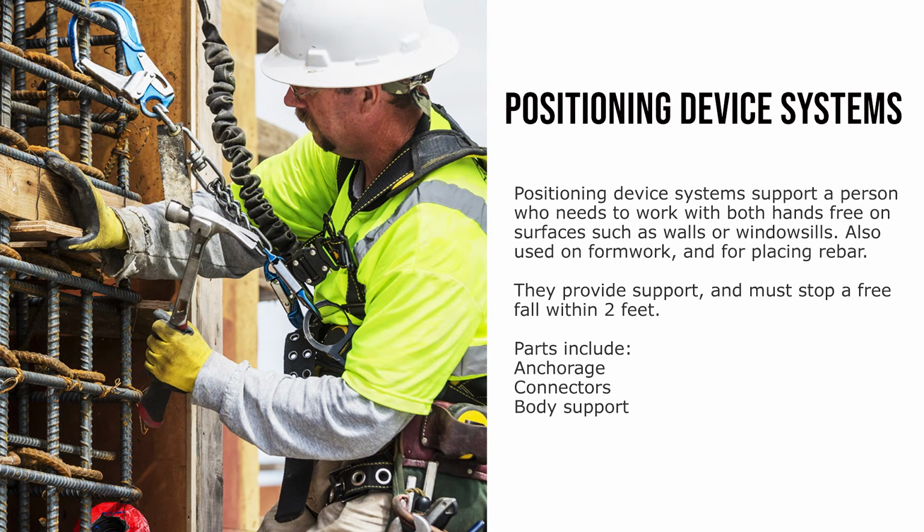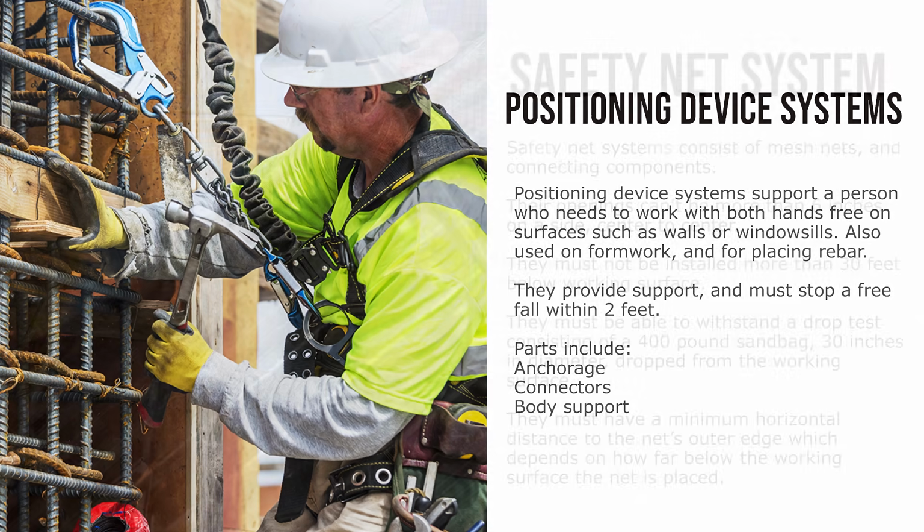Positioning device systems support a person who needs to work with both hands free on surfaces such as walls or windowsills. Also used on formwork and for placing rebar. They provide support and must stop a free fall within 2 feet. Parts include anchorage, connectors, body support.